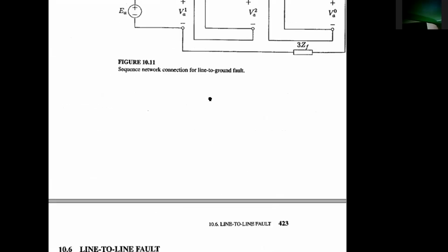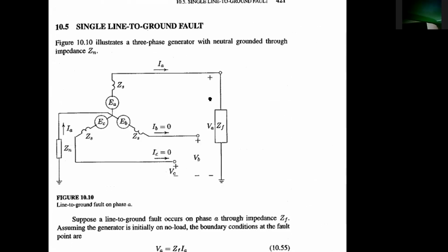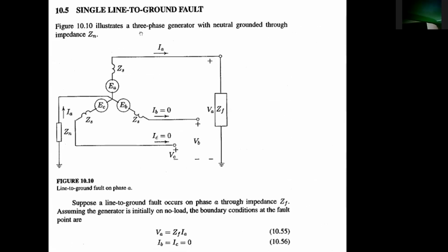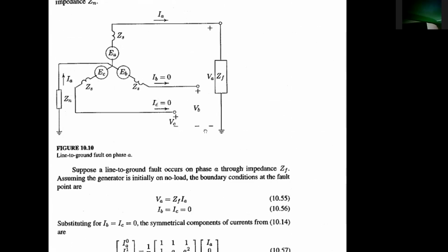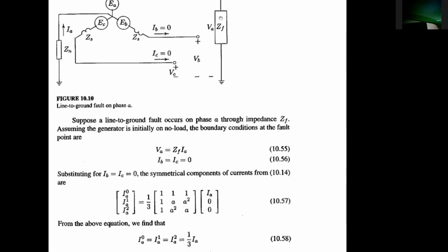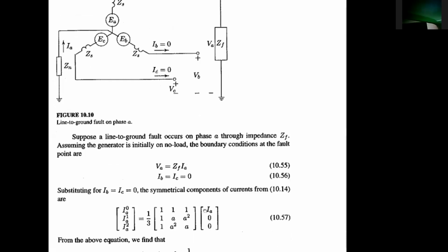Now we can check the earlier class lecture, how we can put their information there. If it is another type of fault, single line to ground, what will happen? Single line to ground case, only IF current will be there. IB and IC will not be there, right? Because you have only the fault path through that phase. So current will only be in the first phase. So the first phase will have IA and IB and IC will be 0 for single line to ground scenario. This part you have to be careful.